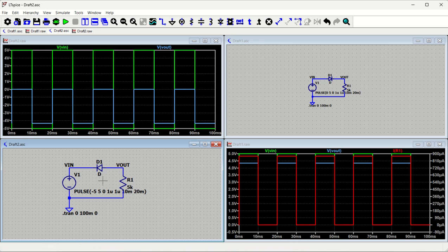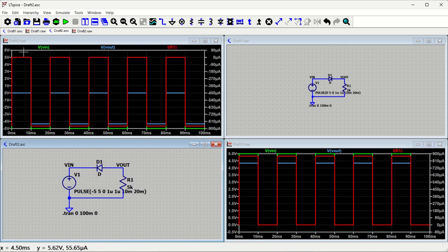Okay, so since this particular voltage is low, that is -5, it is working, and you can see the current across this will be negative at that time. So IR1 is almost, how much is it? Leakage current is there. You can see it is leakage current. Okay, so this is all about diode circuitry.